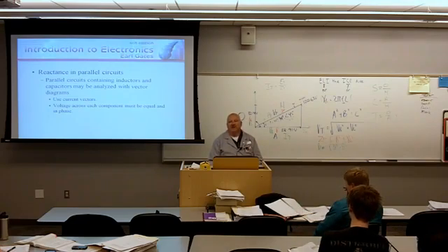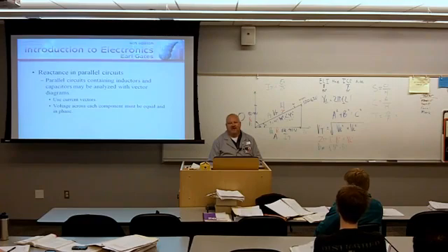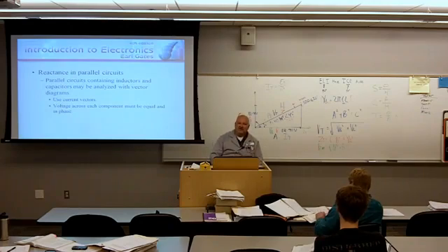What kind of vector diagrams are we going to want to use in parallel circuits? A parallel circuit is also known as what? Current divider. So what kind of vectors are we going to have to use? Current. Can I use voltage vectors in a parallel circuit? Why not? Voltage is constant. Very good. There is no phase shift of voltage in a parallel circuit. What the voltage is the voltage.